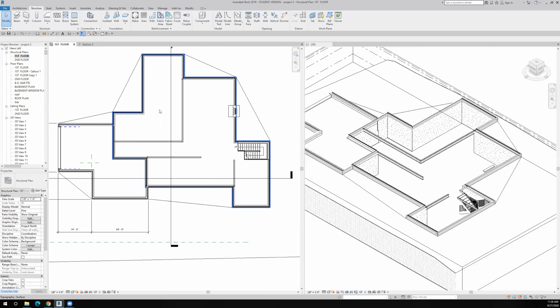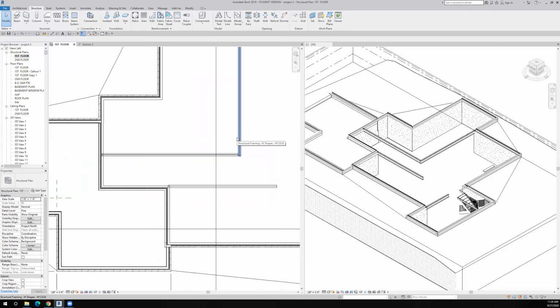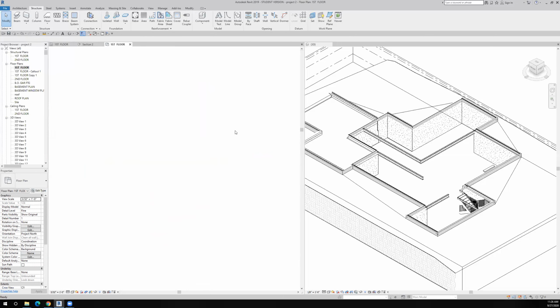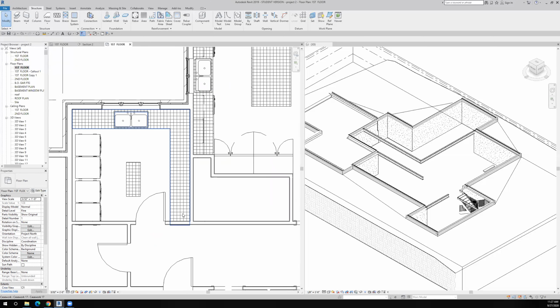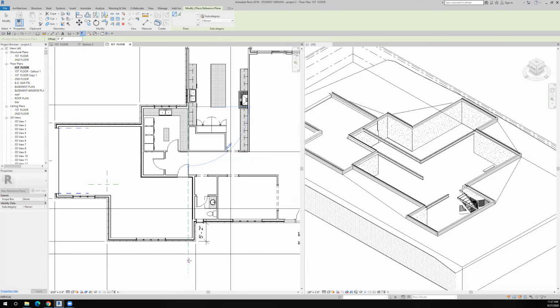So I'm looking at my framing. I'm definitely going to go across this way till I get to here. But then what am I going to do? Am I going to go across this way, or am I just going to go across here? So I think what I'm going to do is put a steel beam in under the first floor. So I'm going to go to my regular first floor plan, and I want to identify where the center line of that wall is. So I'll go over to the architecture tab and put in a reference plane, and I'll just draw it in from here just to there.